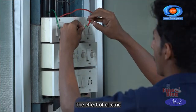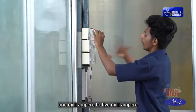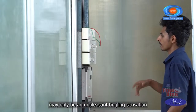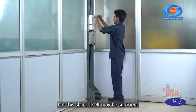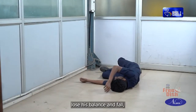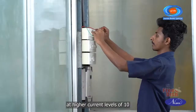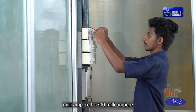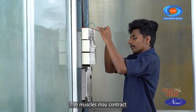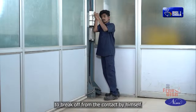The effect of electric shock at very low current levels of 1 milliampere to 5 milliampere may only be an unpleasant tingling sensation. But this shock itself may be sufficient to cause someone to lose his balance and fall, resulting in casualty. At higher current levels of 10 milliampere to 300 milliampere, the muscles may contract and the person will be unable to break off from the contact by himself.